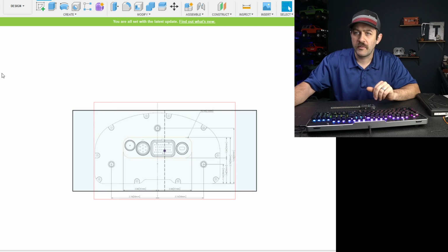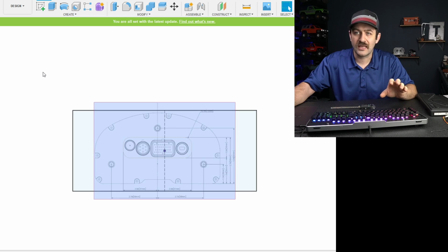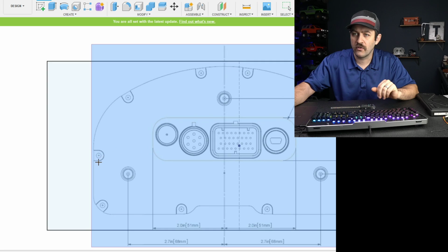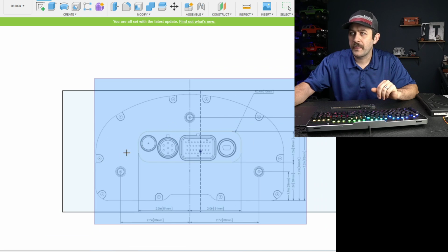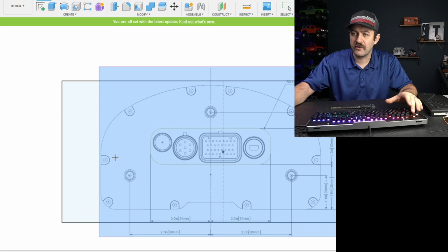Now from here we can go into those canvases and right click on this. Sorry, you guys can't see it for some reason, it doesn't show everything on my screen, but up here there's a little tree that goes down and shows canvases, and then you can right click on the thing that says Racepak and hit calibrate. Now I can click over on this and we're going to go rough on this for now.